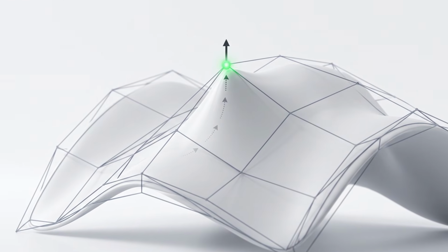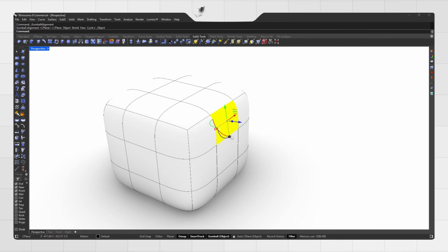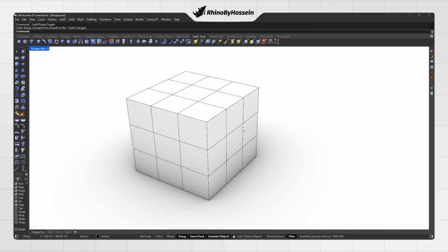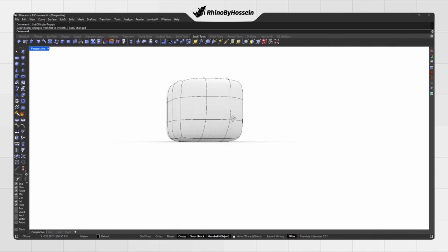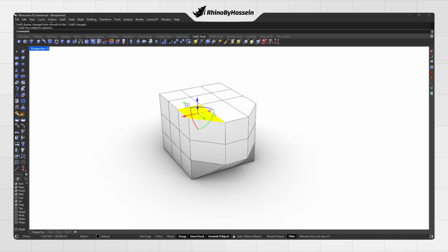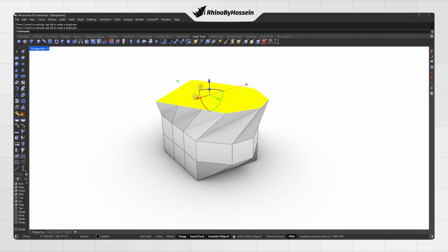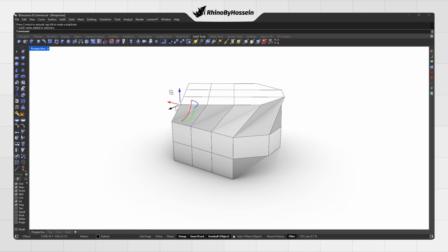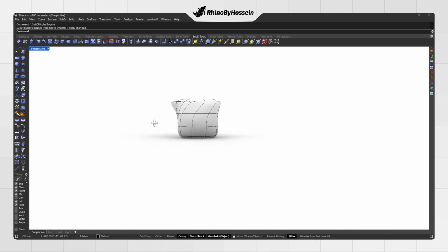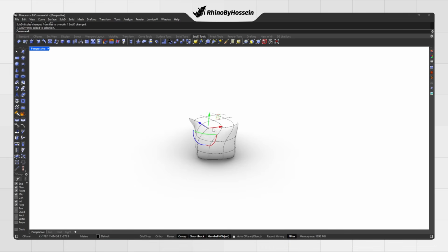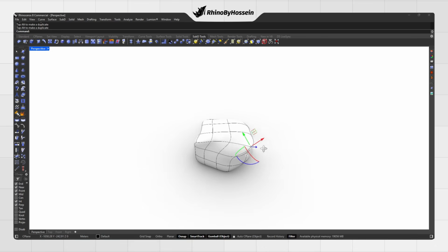During subdivision, the faces are divided into smaller parts, and the positions of the vertices are recalculated to create a continuous and smooth surface. This means that every change made to the control cage affects the final result. For example, moving a single vertex will smoothly influence the surrounding area, while adding an edge can make a shape more controlled or sharper. That is why the most important concept in SubD is the topology of the model, the way vertices, edges, and faces are connected together. A clean topology gives you better control over the form and leads to a higher quality final model.